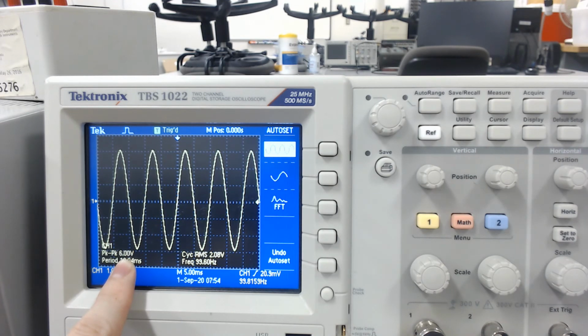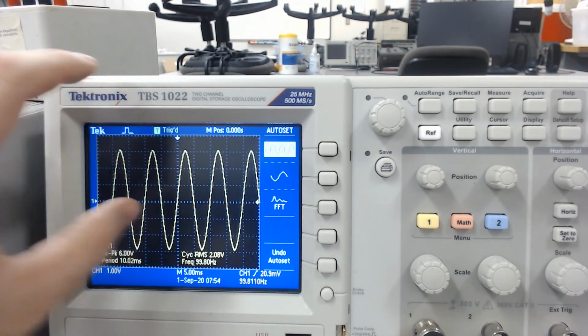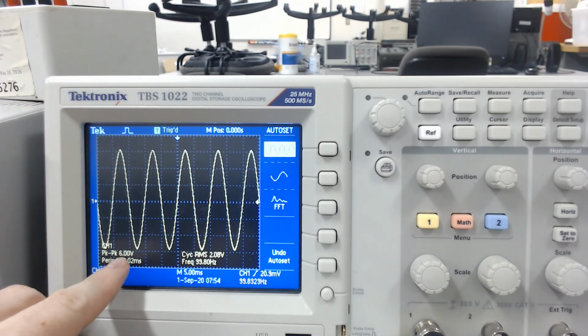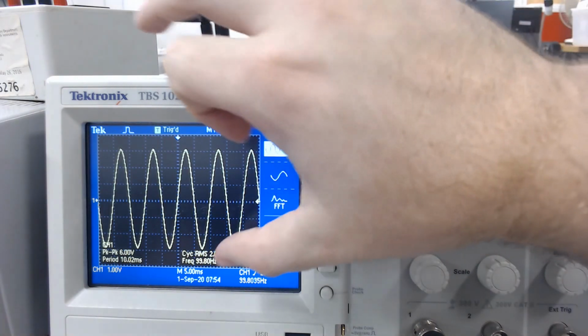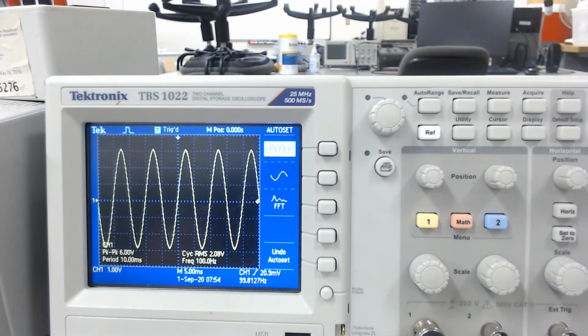So again, as this number down here, this 1 volt, it was 5 volts. The higher that number is, the higher the error you have on your readings. So by zooming in and getting the full picture here, you're able to have less error and actually zoom it into 6 volts, as opposed to, like, it was fluctuating from like 5.8 to 6 before. But now it's pretty steady. So again, having it utilize the full range of the oscilloscope really helps you get those readings.